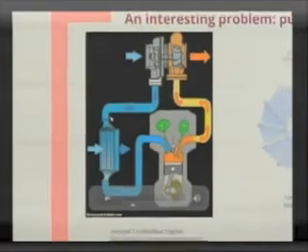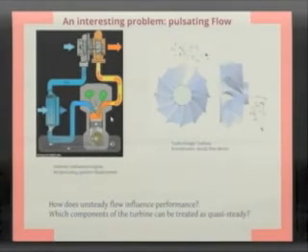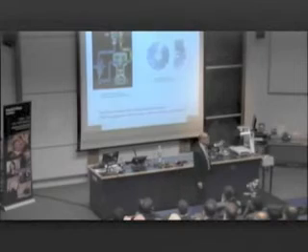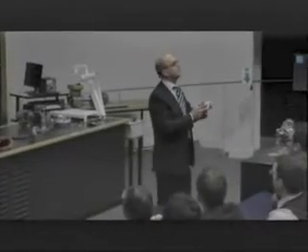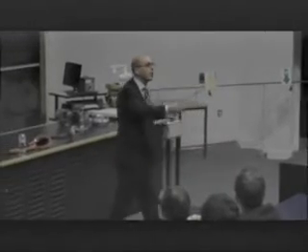Oscillations, no good. This is what for many years I've talked about as a marriage which is not great. It's a bad marriage. Because you have a highly oscillatory device which likes oscillations by nature. It is designed to be so. And this unhappy marriage makes this guy very unhappy because the turbine doesn't quite like all these oscillations. This turbine is designed to run at some particular conditions with some particular flows. This is the turbine inside the turbocharger. And therefore, there are some limits as far as how you can make the flow approach this device.